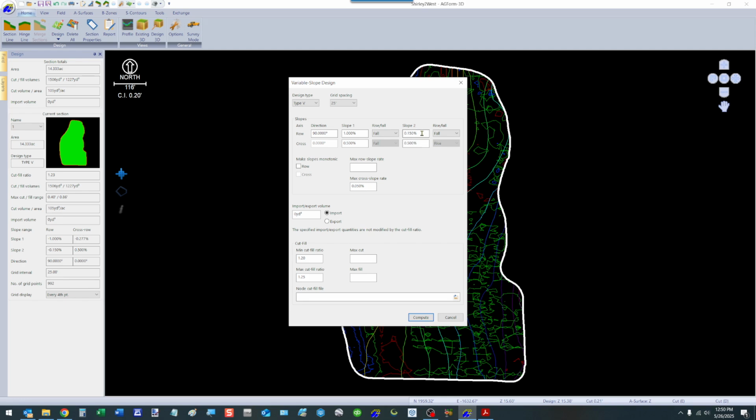So in this case, we've got 1/10 fall, and we have 5/10 fall. So 3 times 0.15 would be 0.45. So this would be 0.45. 4 times would be a 6/10. Typically try not to go over half a foot.